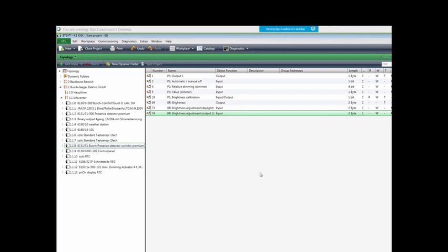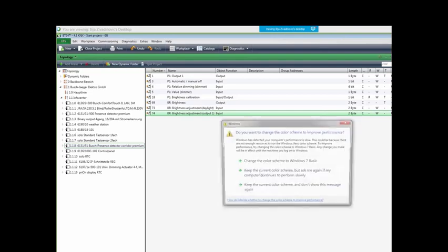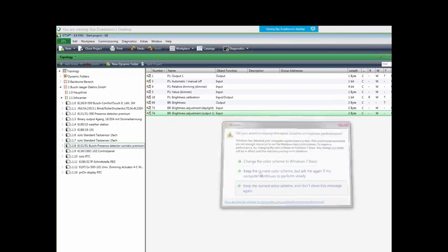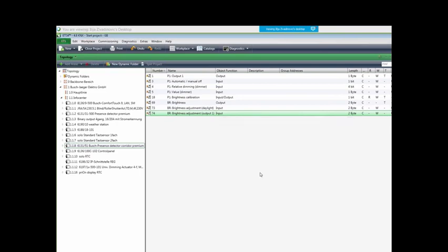Then it will monitor, okay, I know the daylight, then I know the value of 100% artificial light, and store the value. Then it will reduce the dimming light to 90%, monitor and detect the value, then to 80, 70, and so on till 0. And it will internally store its own calibration curve.